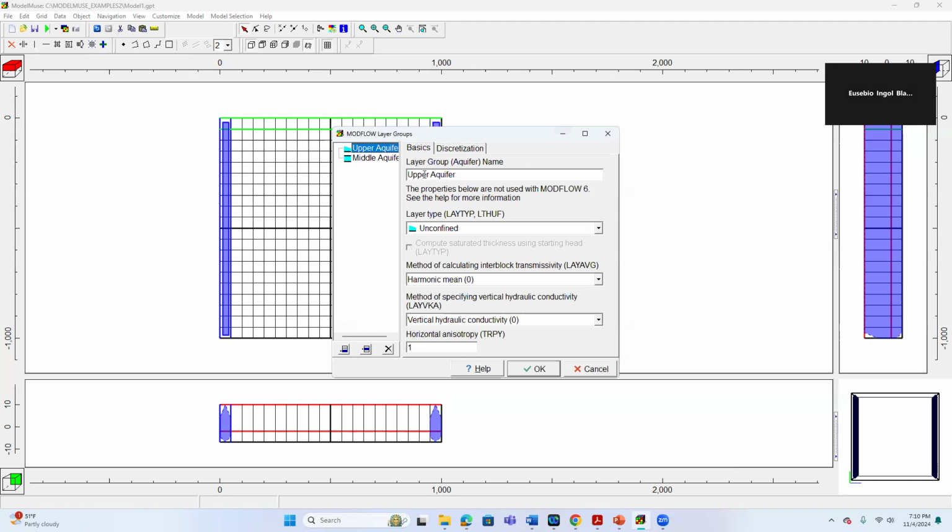And for the confined layers, the second one, we were talking about the confined aquifer. A confined aquifer layer is under pressure, we know, between two low permeability layers, okay? In this case, when we set up the confined layers, the hydraulic head in this confined layer can rise above the top boundary of the layer, but it doesn't change the thickness, okay, the thickness.